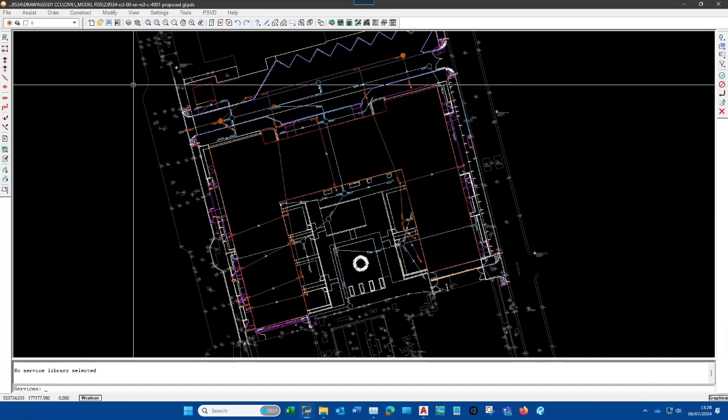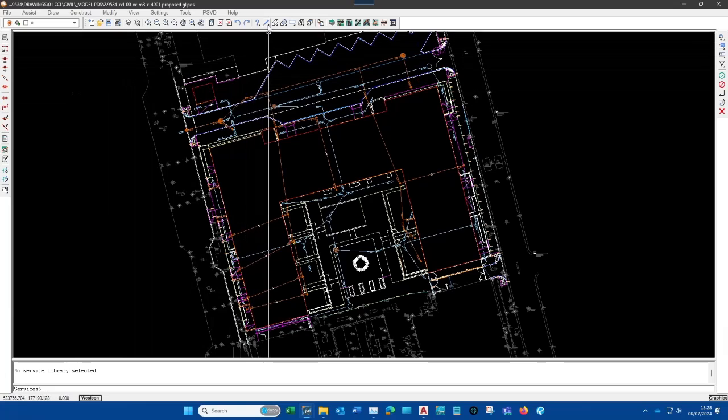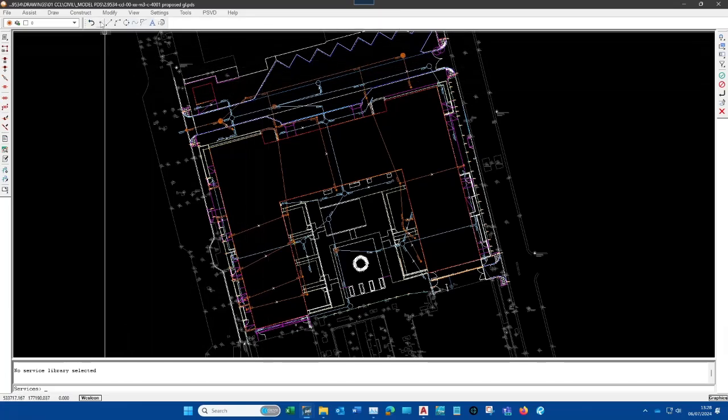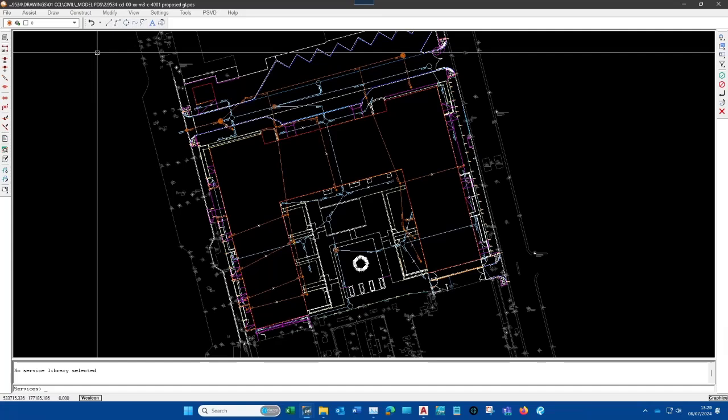If we go to the draw toolbar, which is the pencil, here you have draw, point, line, arc, circle, string, fillet, text, and such. One thing I would point out, I'm not too sure I have done it already, is that if you have a list of things in one area, PDS generally tends to list those same things in the same order.